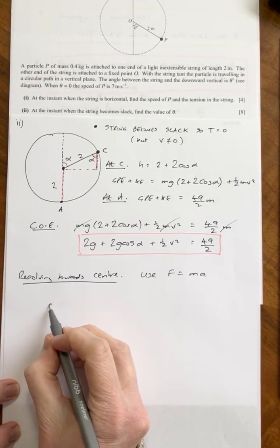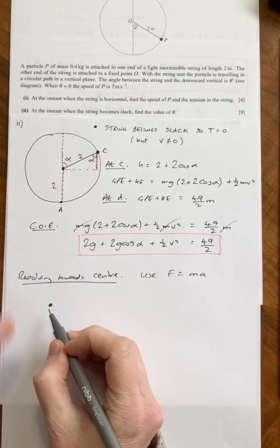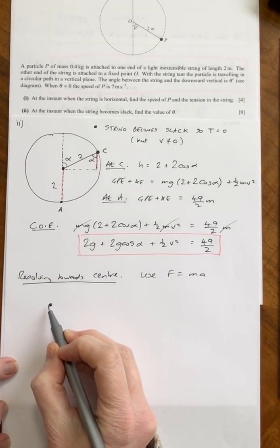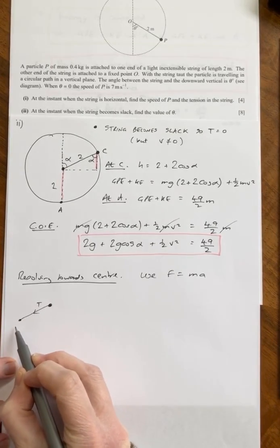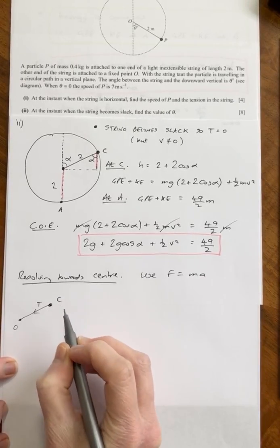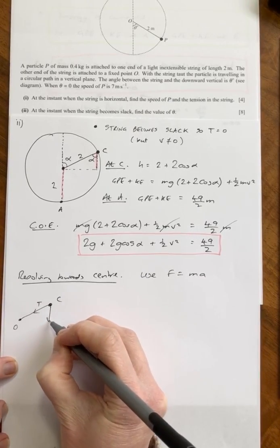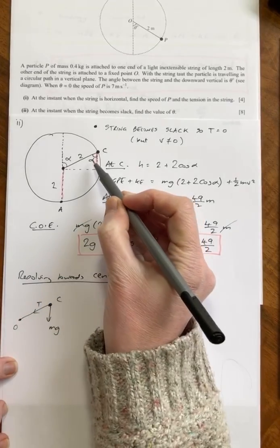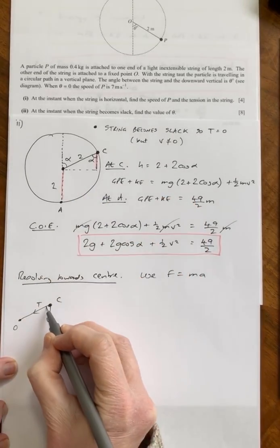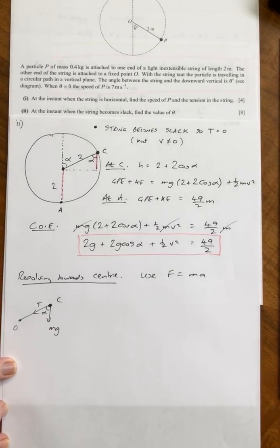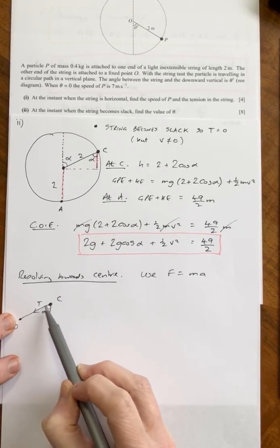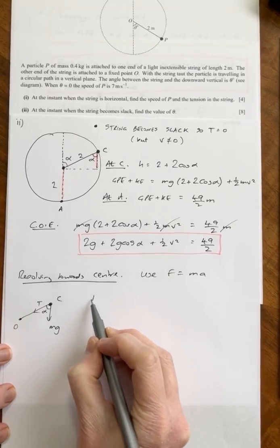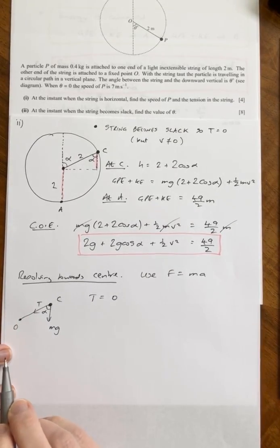And if I just draw a little sketch, I know it's contained in there, but that was really for lengths. This diagram here is going to be to work out forces. So there's the string. That's the centre of the circle. This is part C. And here is my weight force acting down. So it's essentially this triangle here, but I've just drawn forces on rather than the lengths. T actually is equal to 0, but I've drawn that in because I can see the triangle and I can see where the string is. So let's just make a note there. T is equal to 0.